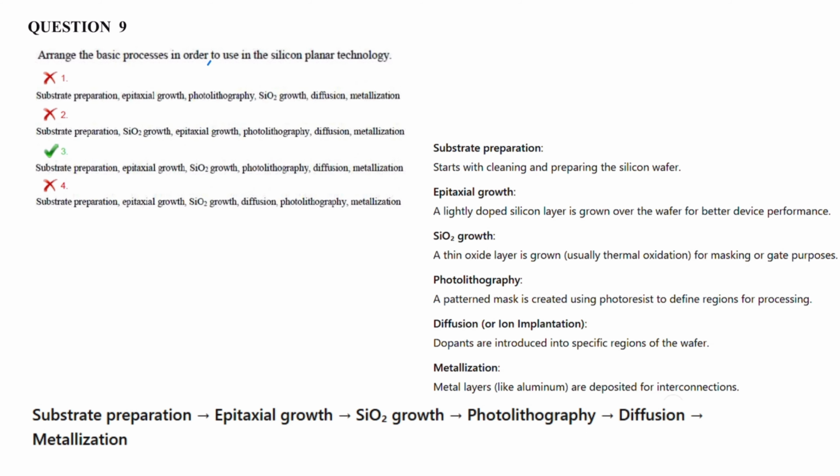So correct answer is option 3. Substrate preparation, epitaxial growth, SiO2 growth, photolithography, diffusion, metallization.